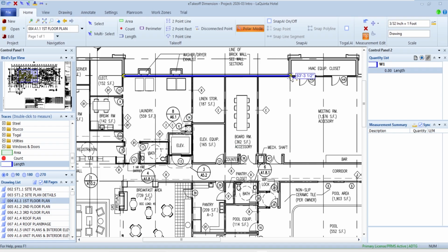So they're assuming that with things being a straight line, I could just click a point, click a point, click a point. So it's basically faster than trying to deal with the X and Y axis at the same time, or all 4 axes at the same time. That way I only have to really deal with the 1 axis. If I hold down my control key, it would release it, so if I do want something that's not at a 45 degree angle, I can still come back and get something else in there.